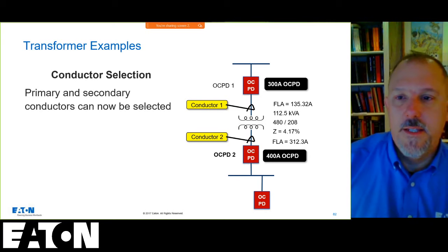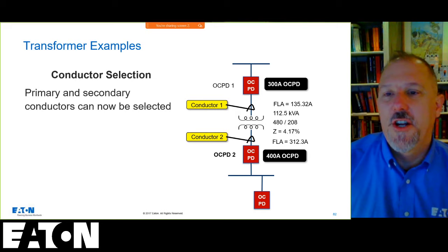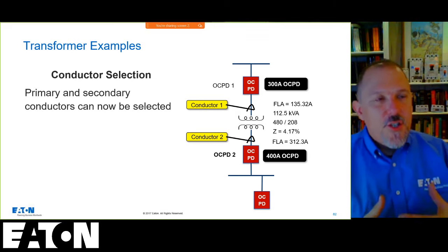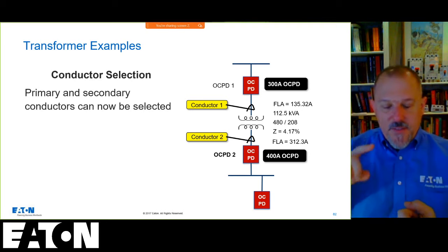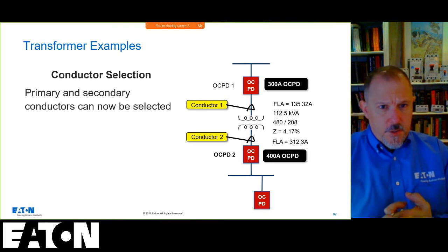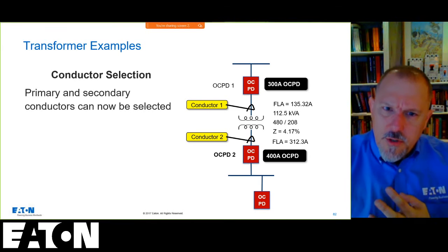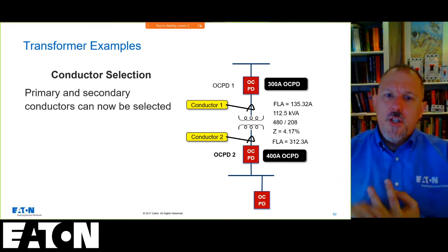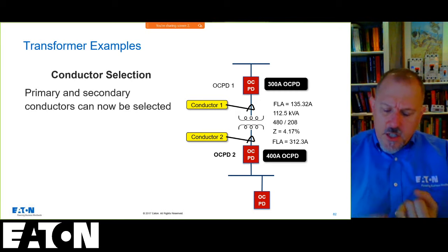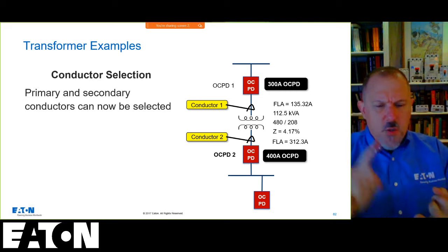All right. So, can we plot panel board damage curves? No, Luis, Diego, we do not. So the damage curves that we have: conductor damage curves, transformer damage curves, motor start curves, and there is a motor damage curve as well. I'm going to talk about that tomorrow. But we don't have panel board damage curves. We don't have switchboard damage curves.